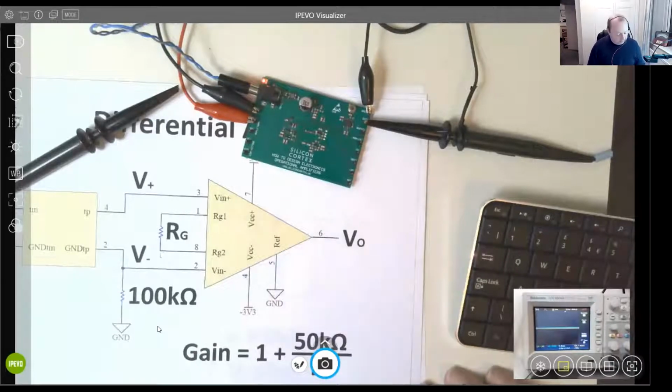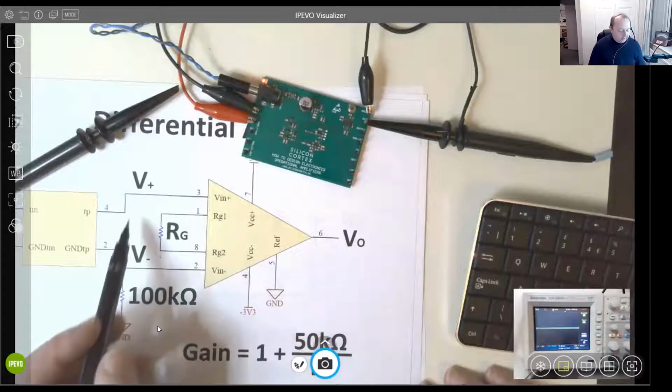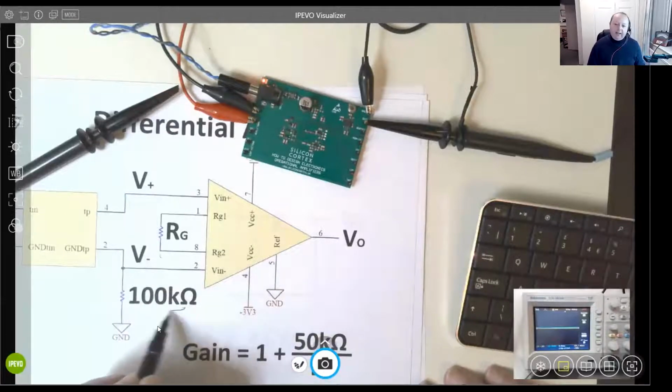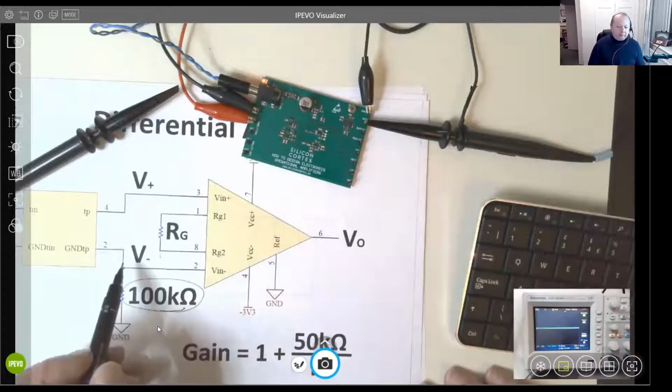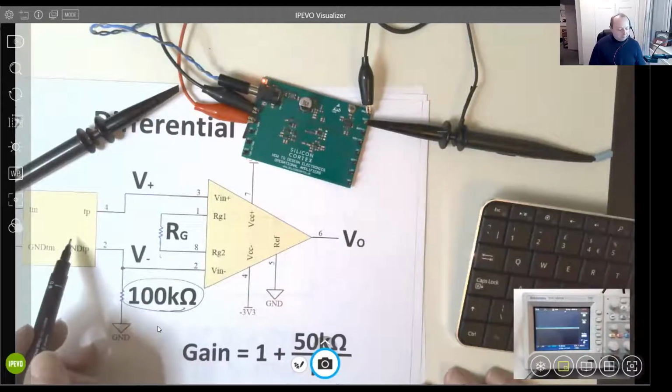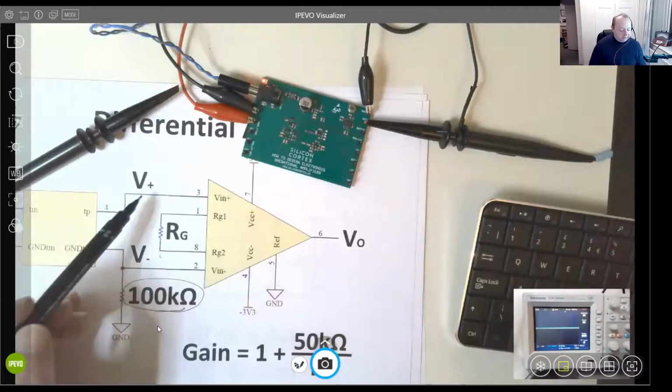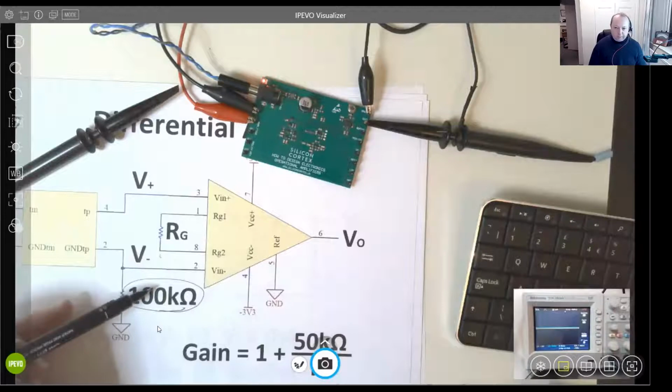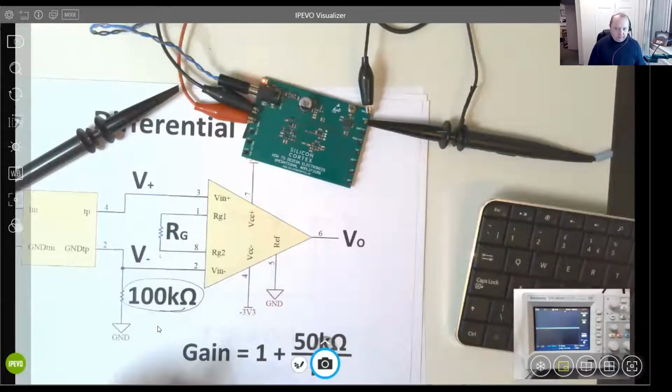And what I discovered was, in order for the differential to work correctly, I had to add an extra resistor in order to give it a reference to work, particularly for this type of sensor, a temperature sensor, where it didn't work to have the signal floating. It was causing me all sorts of problems. So it just seemed to make it work by adding a large resistor to pull down one side. So it's then got a reference to ground, is probably what made it work. So that's just a top tip if you're using differential inputs. I learned that one the hard way.